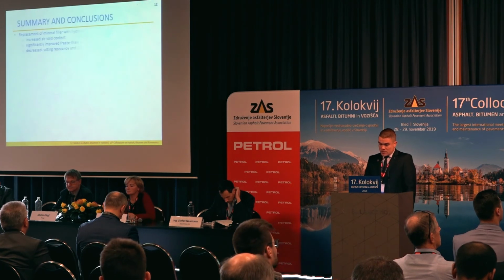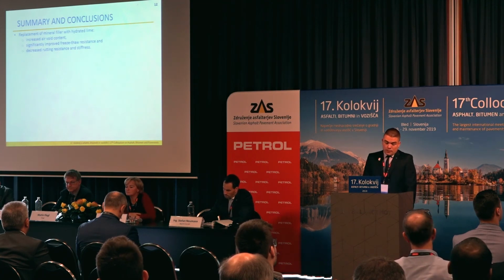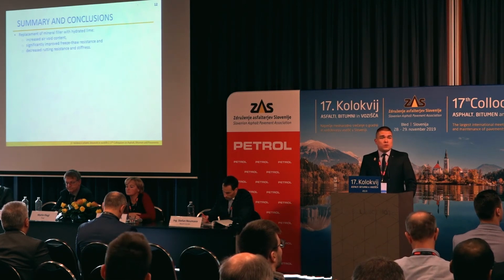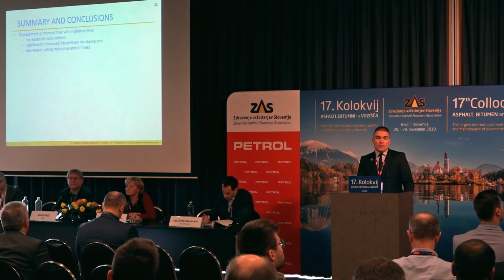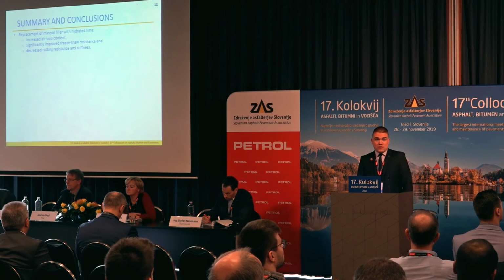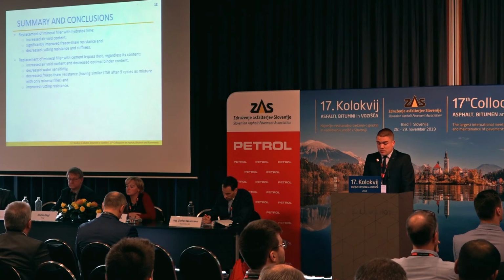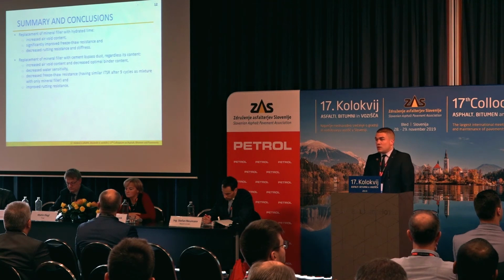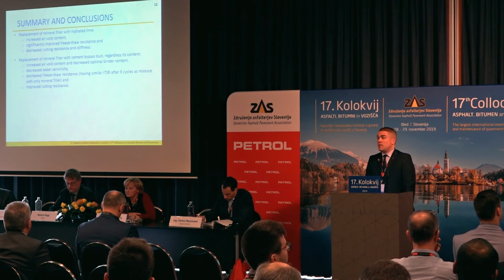And finally, here are some summary conclusions. So replacement of mineral filler with hydrated lime brings increased air void content. It significantly improved freeze-thaw resistance and decreased rutting resistance and stiffness. This is a bit unexpected, but similar behavior has been found also in previous studies. Replacement of mineral filler with cement bypass dust, regardless of its content, increased air void content and decreased optimal binder content. It decreased both water sensitivity and freeze-thaw resistance, but it improved rutting resistance.